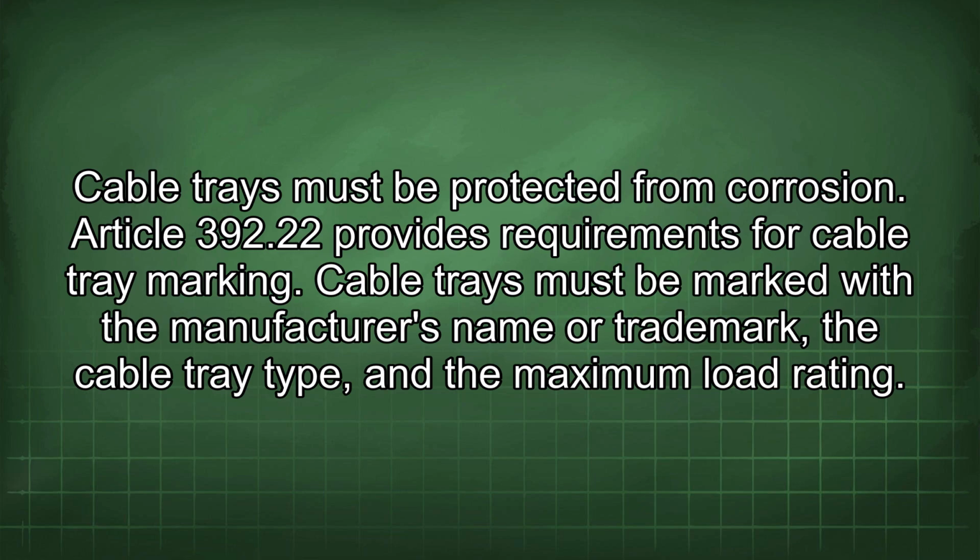Article 392.22 provides requirements for cable tray marking. Cable trays must be marked with the manufacturer's name or trademark, the cable tray type, and the maximum load rating.